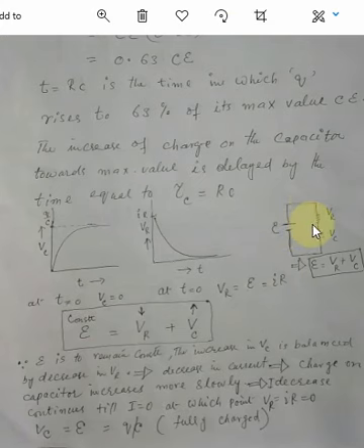So if the voltage across R decreases, it means that since the resistance R of this resistor is constant, voltage V will decrease only if I decreases. This is constant, so if I decreases, then IR will decrease, or in other words VR will decrease due to the decrease in the current. So when this current decreases, it means that the charge on the capacitor will increase more slowly.